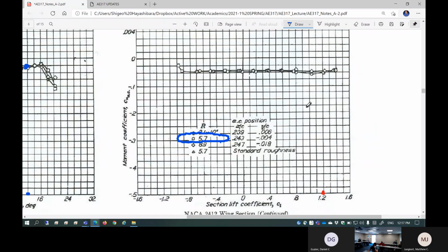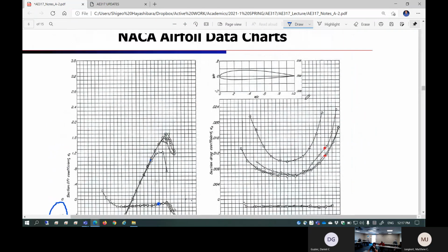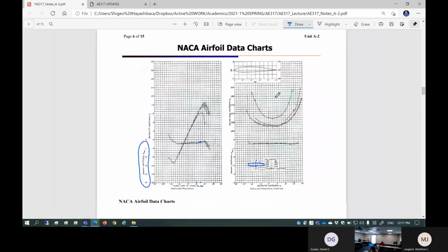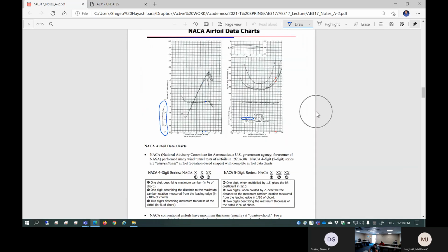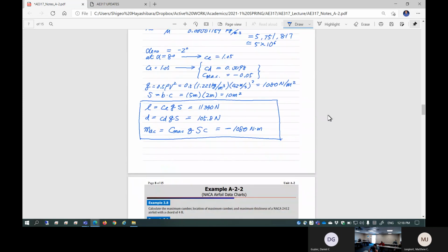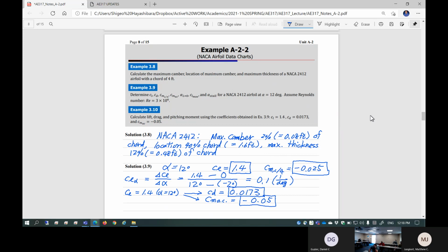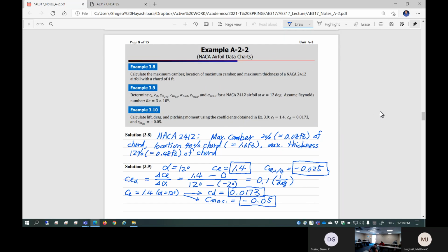Now, the reason is you have a thickness and also camber. So this is a fairly thick cambered airfoil, right? This has a tendency to shift the aerodynamic center slightly forward. I think we talked about that in Aero 1. It's pretty close to quarter chord, but not quite. Still, people say it's fairly close enough, so let's choose quarter chord as the aerodynamic center. You can do that. So this is the thickness plus camber effect of a fairly thick airfoil.